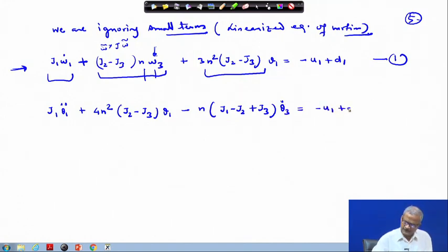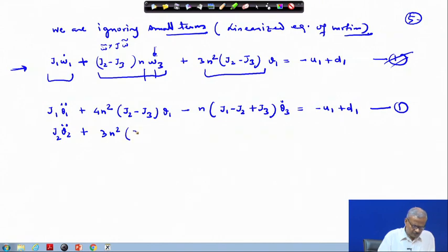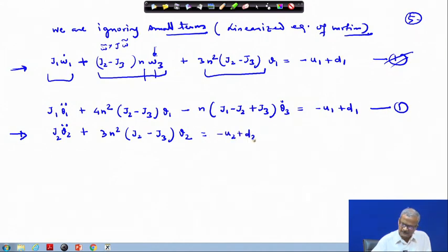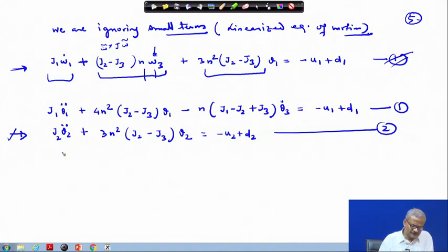So, look back into those lectures and you will get these equations. And we have seen that in the spin stabilization the motion about the two axis gets decoupled from the other axis. Okay. So, independent of the 1 and 3 axis, we can control the two axis motion, which we call the pitch axis motion.